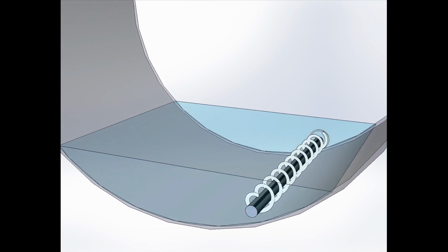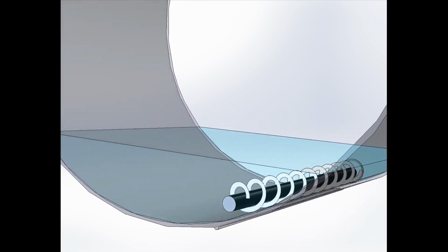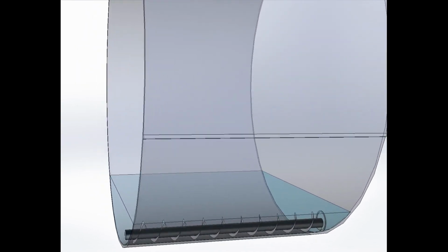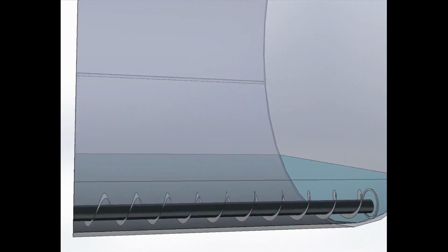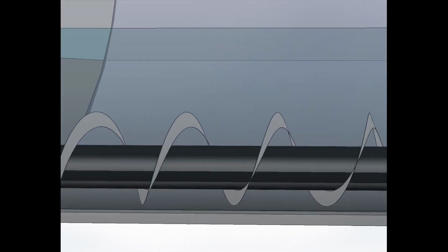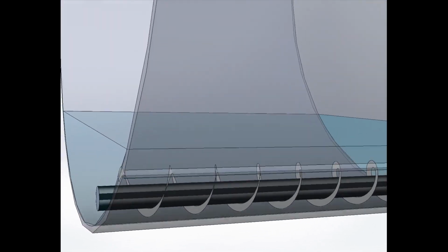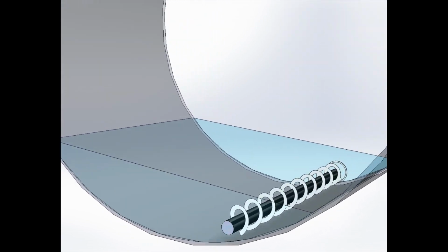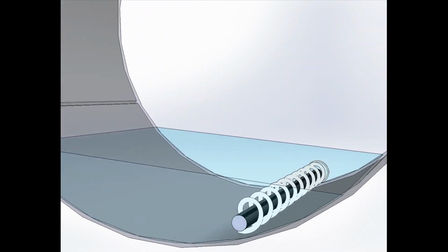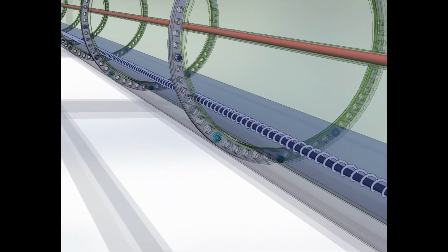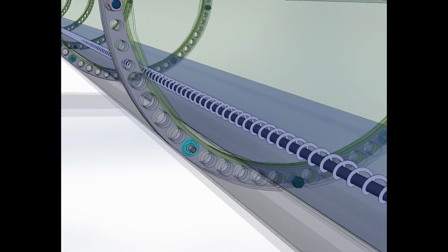To increase the impact of the screw edges on the heated surface in order to clean the surface, inside the spiral there is a heavy metal rod that rolls along with the spiral. In this case, the inner edges of the spiral also clean the surface of the rod from deposits. The small thickness of the spiral metal tape ensures its elasticity and periodic oscillations of the turns relative to each other, which creates conditions for the detachment of deposits from the surface of the tape itself. In this way, conditions are created to maintain the functionality of the system for mechanical cleaning of the heating surface.